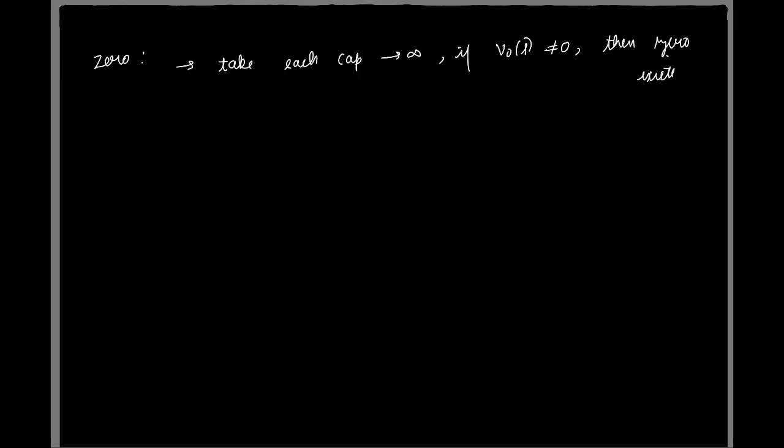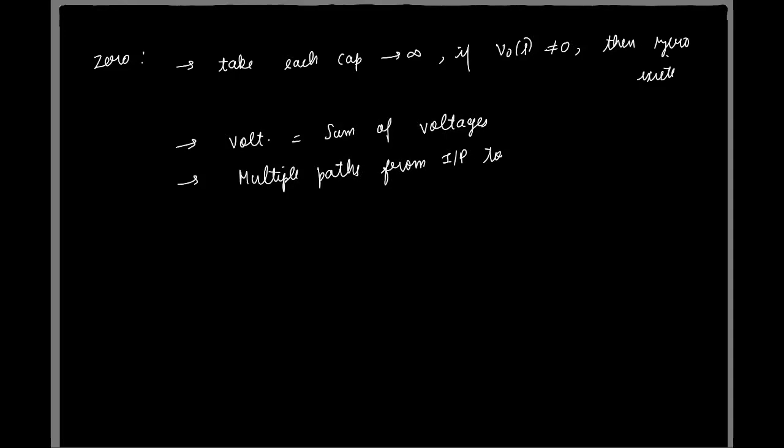And we also saw a slightly more intuitive way to find if you have zeros or not, which is to observe if the output voltage is a sum of some voltages with different phases, or you see if you have multiple paths from the input to the output, multiple paths for the current, and the paths must have different phases, right?